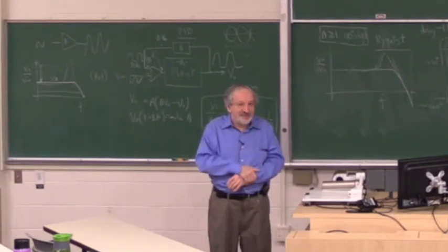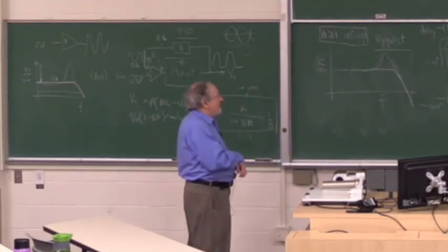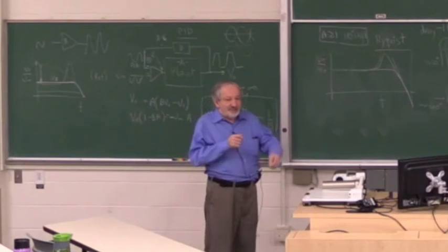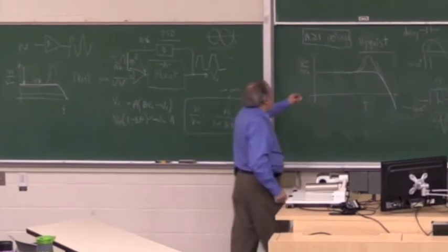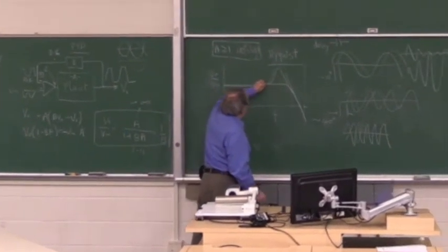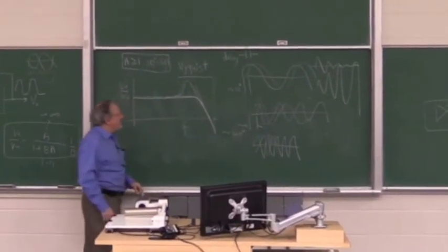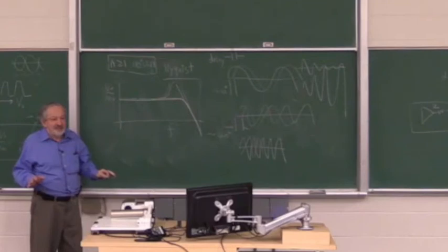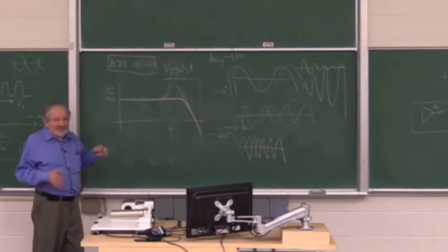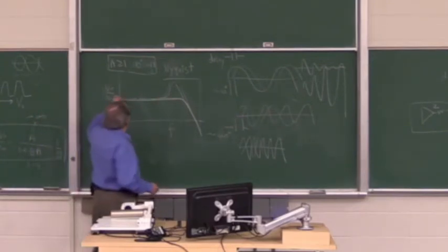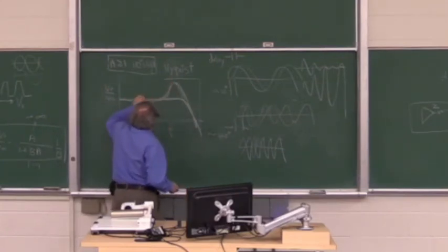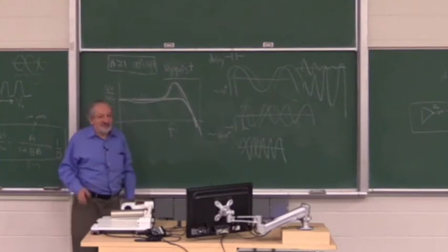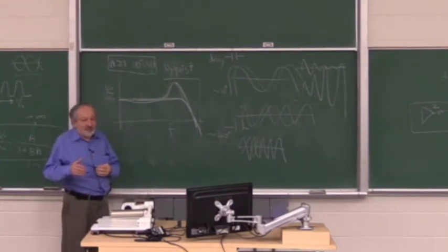or mathematically show stability. Okay, so basically when you have an amplifier and you connect it with feedback, and you test it with a scope and oscillator, if the graph comes out like this, you don't worry at all about stability, because you know there is no tendency to oscillate. But if you plot it and it looks like this, then you start getting a bit worried, because somewhere there's a phase shift developing which can destabilize it.